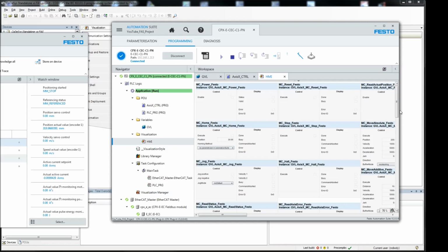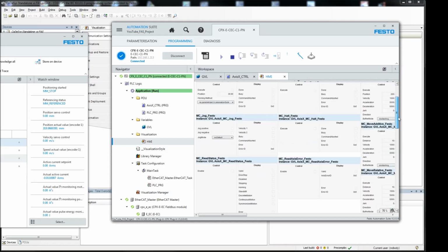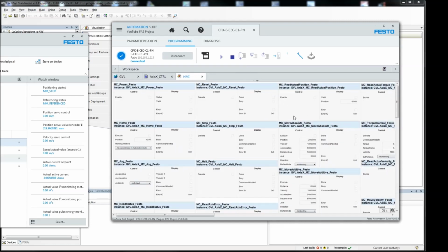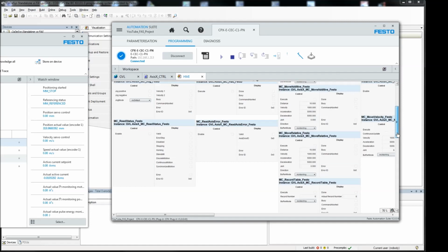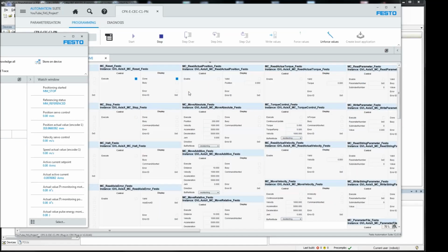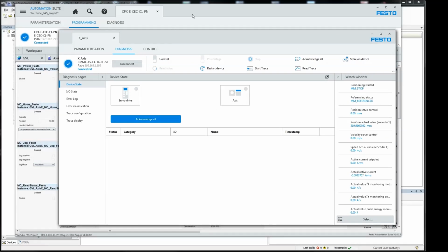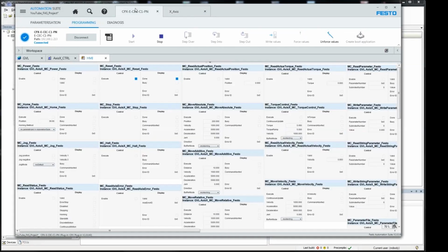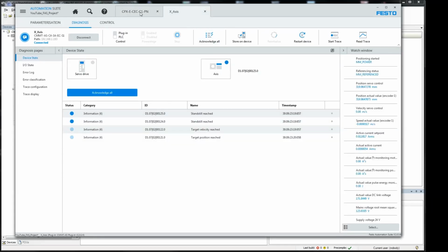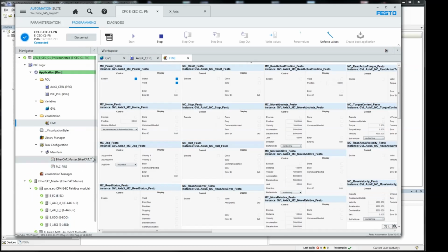I have, where's my MC reset, jog, home. Looking for my reset. So I just clicked the reset, and now we've cleared the errors. Here, I'm just going to put this back so that click and drag back. And so we've reset the errors, turn the MC power on. Now we get the home. You'll see here that we're all good. This is all good over here. And this stays on. At any given time, I can read my position. I'll just leave that running.